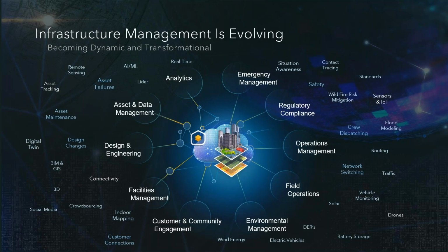And I'm sure a lot of you out there have seen these things coming into play as well. And the ones I wanted to highlight were asset tracking. We mentioned the age of pipes, the age of assets. GIS can be used to start better answering some of those questions and help address those problems that you might start to see. Also, the connectivity. We can visualize our pipes, you can visualize the system, but I want to understand the flow. I want to understand how the connectivity of these actual devices and these assets are going to impact customers or impact the performance of the network.